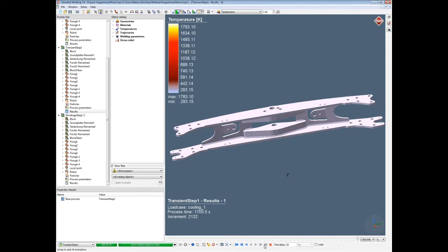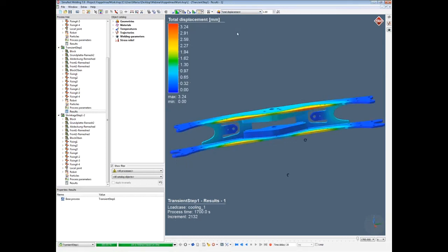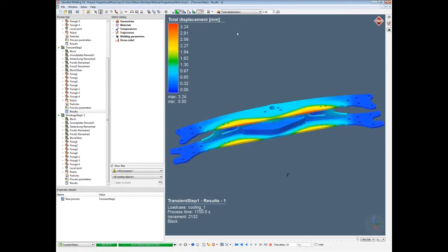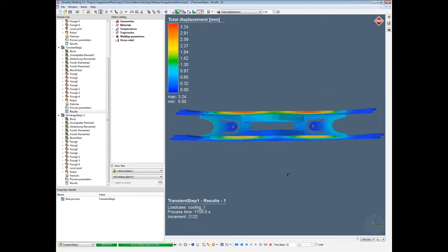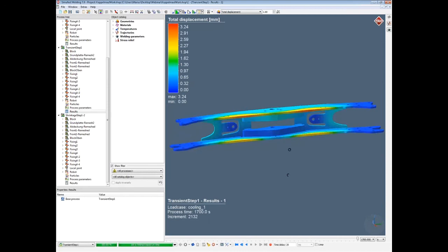And when we look at the final result of this, you see there is some critical deformation here, which would make it harder to add additional parts after this or to even take it out of the clamping system. And this was really the problem they had here. This simulation here was not a solution for them, but it was a good measure to see what kind of clamping system they need to create for this.